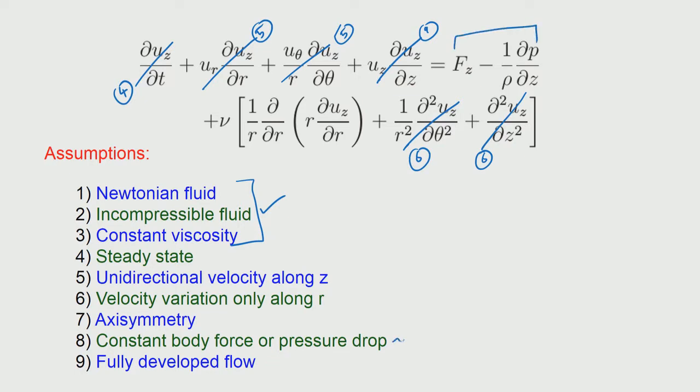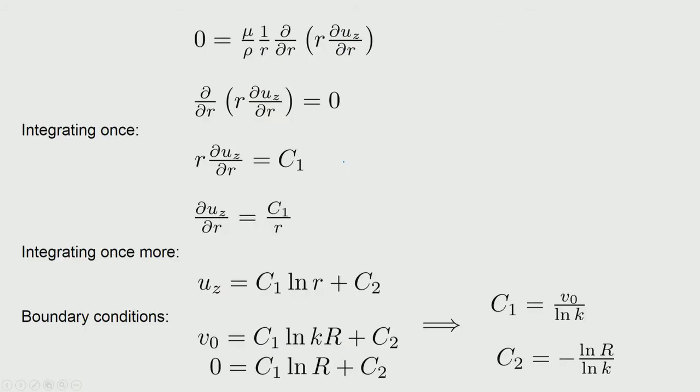Okay, so 0, because we say that the flow is because of only the boundary conditions and not because of anything else. So we just drop this, which leaves us only with these terms, and so that term we basically write it, and this is now the trivialized form of the Navier-Stokes equation for the z component, and when we integrate twice, then we get the logarithmic term. Now in this situation we are not dropping the logarithmic term, because the domain is not containing r goes to 0. So we do not have a problem. Okay, so we have this as a functional form.